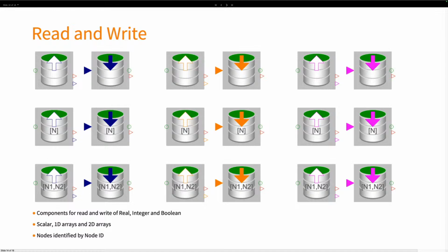In OPC UA, nodes are identified by either a numeric integer ID or a string identifier. One thing is that OPC UA has a richer list of types than Modelica that is used in System Modeler. So for example, it has unsigned and signed integers in all combinations of the usual width variants, whereas in Modelica we only have one basic integer. So when writing data, we must also specify the specific OPC UA data type that should be used for the write request.